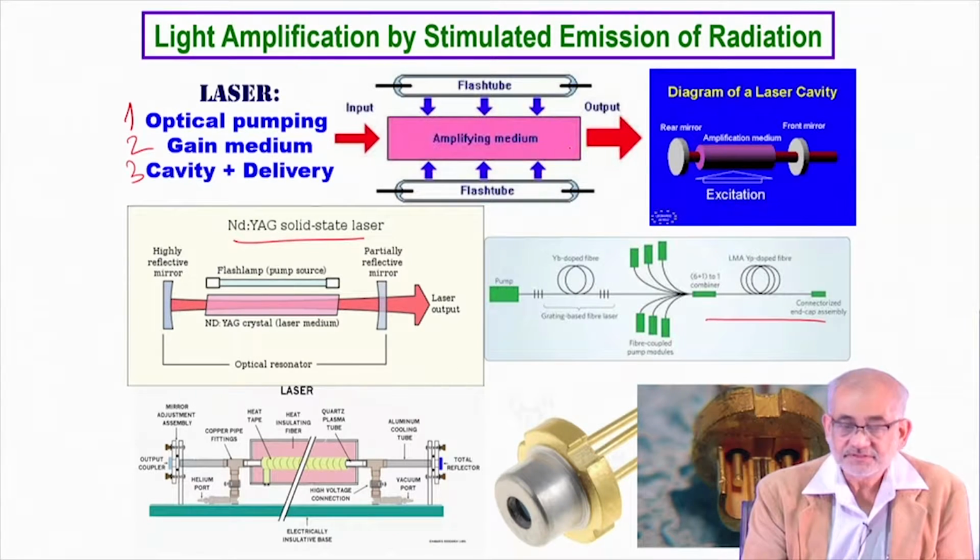Since I mentioned the fiber laser being one of the most widely used these days, that happens because it's very convenient. The active medium and the delivery medium are the same. So essentially long optical fibers, and some of them come with pumping devices, which could be diodes that will pump energy into them, and all of them will create a bundle, and that's where they get combined.